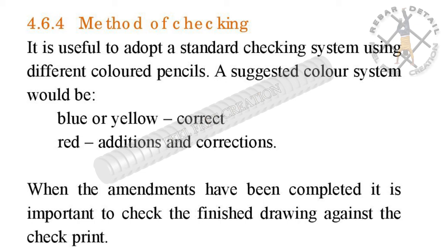Other than yellow or blue not recommended for highlighting purpose, because if we make red mark on other color it is not clear enough to detailers. When the amendments have been completed it is important to check the finished drawing against the check print.